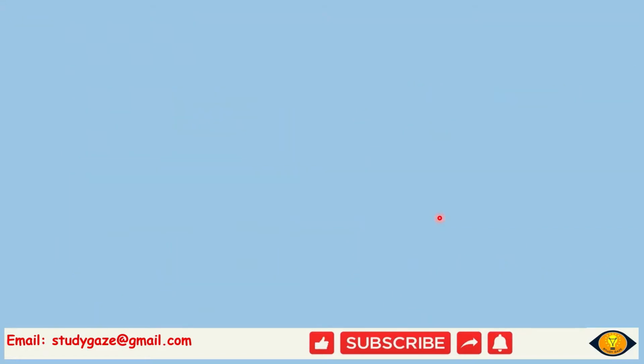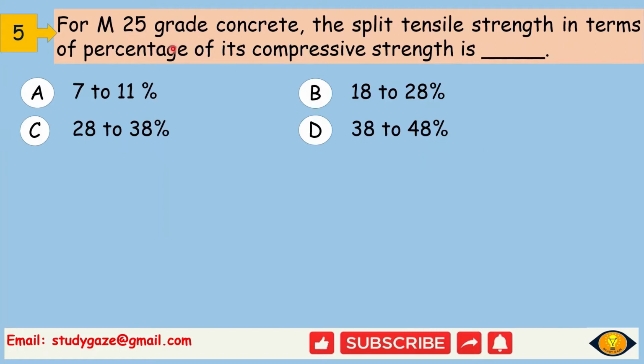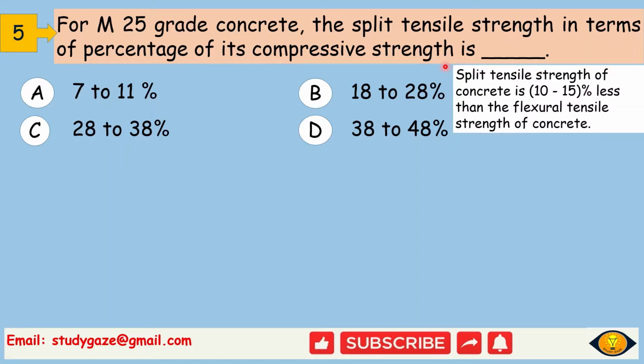Next, for M25 grade concrete, the split tensile strength in terms of percentage of its compressive strength is? The split tensile strength of concrete is 10 to 15% less than the flexural tensile strength of concrete, and the flexural tensile strength of concrete is almost 10% of the strength of the concrete. Okay, it is total 7 to 11%. The answer will be 7 to 11%.